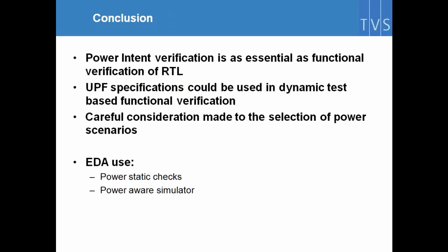So as a conclusion, UPF is an extension of the RTL. It should be seen as part of the design. As such, it should be verified. So we need means to verify the power intent of your design. Some people say things that are not verified don't work.